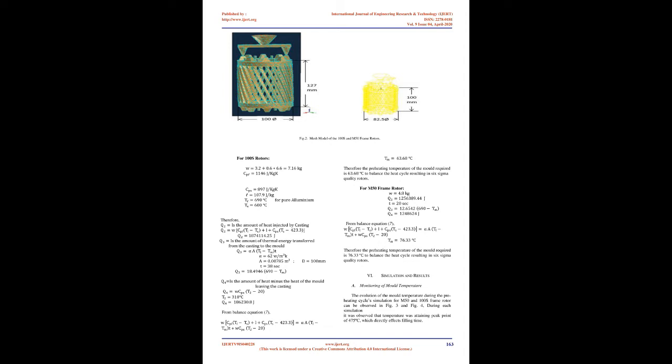Various process parameters. In a practical die casting process, it is quite tough to judge the exact cause for a particular defect because they are quite intuitive, so first of all, it is required to identify process parameters that can affect the process considerably and can change the output with reasonable weight. A cause and effect diagram is drawn for casting defects as shown in Figure 1.